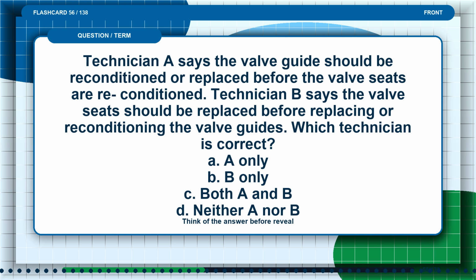Flashcard 56. Technician A says the valve guide should be reconditioned or replaced before the valve seats are reconditioned. Technician B says the valve seats should be replaced before replacing or reconditioning the valve guides. Which technician is correct? A only, B only, C, both A and B, D, neither A nor B. Pause and think of the answer before the reveal.